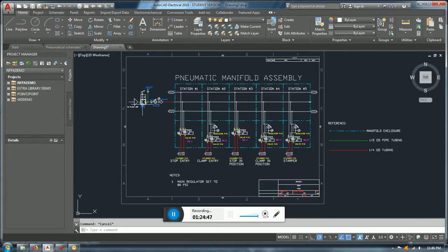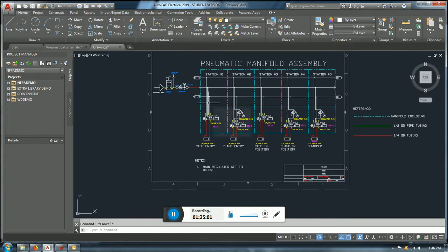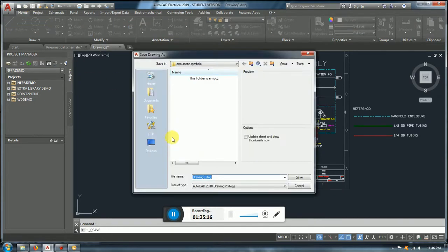And so those are basic. These things are basic. Maybe that one not. These other ones are basic. We need that on-off valve, and we need the manual valve, and we need the filter regulator and lubricator. And now we have the main thing, or the objective for this machine, which is going to have these different solenoid valves. Here are some with regulators to control the force, some not needed, to control each one of these cylinders. Okay, so I'm going to save that.